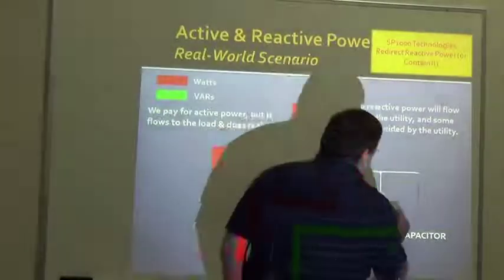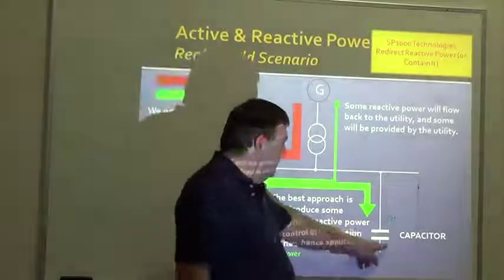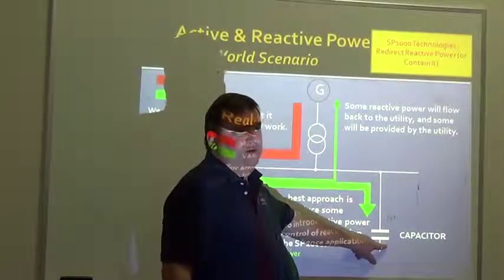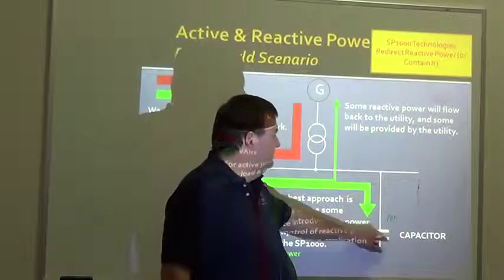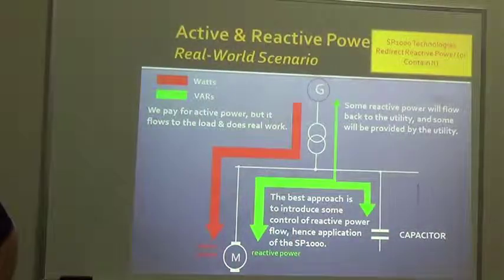And we're doing it with the microprocessor. So that's even better, because this decides when and how much capacitance to put on each phase. And all the phases don't need the same capacitance, because the loads are never balanced. The voltages are never balanced. So why apply the same capacitance to all three phases just because we're too lazy to put intelligence into the system?